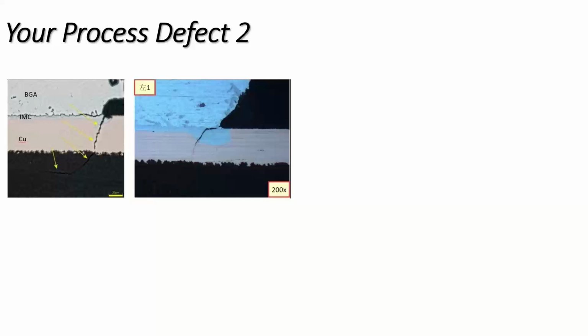Now another part of the equation may be that conformal coating has a part to play. It's not good practice, not ideal practice, to completely encapsulate and underfill a package unless you know that the conformal coating expands and contracts at exactly the same rates as the package, the balls, and the substrate. And that's what an underfill is. But a conformal coating material isn't necessarily exactly the same in terms of expansion coefficient. So you need to know that as well.